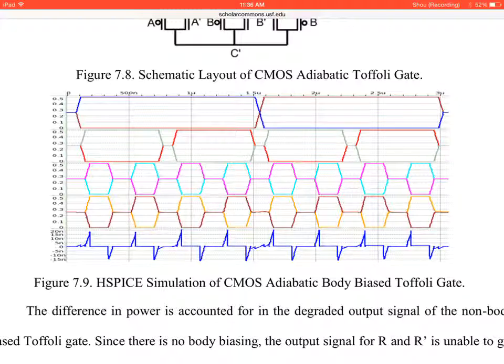So the objective is, you can circumvent all of the software security by doing something known as the side channel check, by figuring out the average power consumption. So I was trying to figure out how to make circuits that consume consistent power. So I used dual rail pass transistor logic, which is A and A bar input for every single input. And you guys know what pass transistors are.